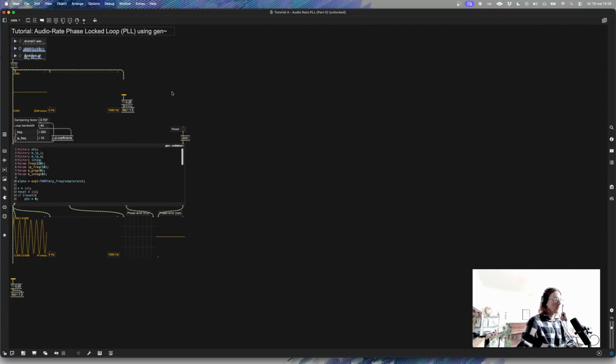We could also do this inside here, but since this is fairly straightforward using basic Max objects, we will compute the signal using regular MSP objects. And we can, for example, use the average object, which takes an averaging interval, which we maybe can have as a parameter as well.